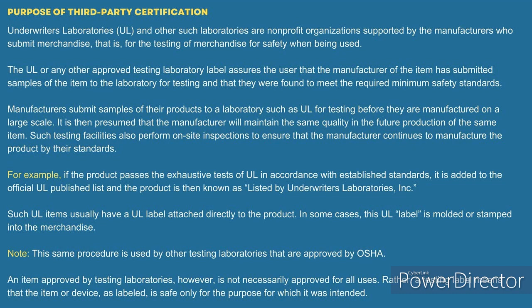If you were going to do something where there's a receptacle right inside the foyer, I'd just say get a GFCI device and put it on there, because that's where you're interacting with it outside, and you would need GFCI protection. I'd argue it doesn't matter if it's considered a dry, damp, or wet location. You're still interacting with the cord and plugging in from outside.